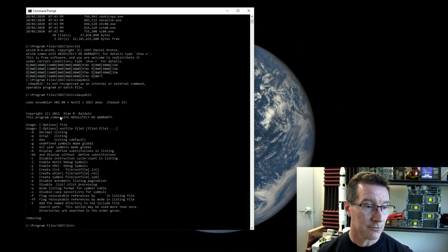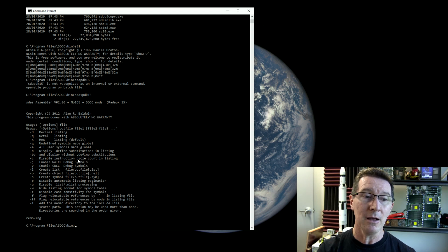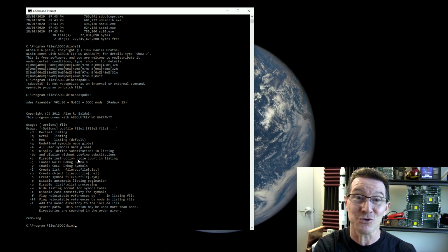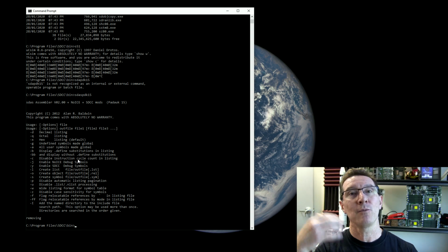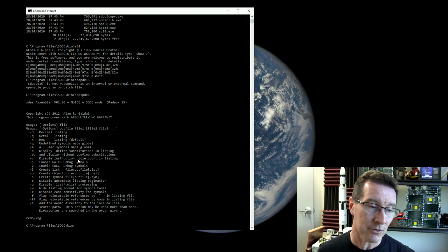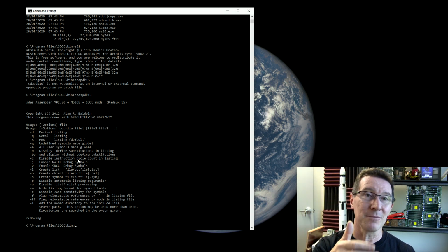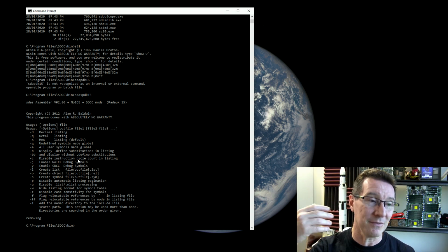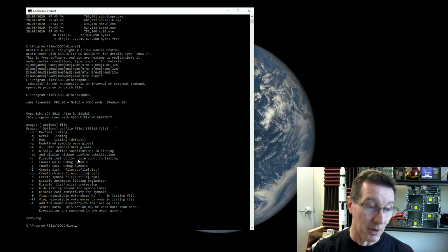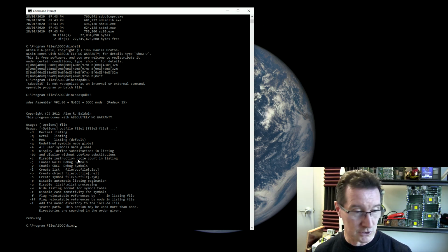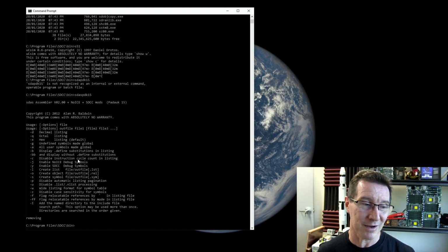That's the assembler written by Alan Baldwin. Good on you, awesome effort. Absolutely no warranty implied. But yeah, this is what the compiler will call. It'll call up this assembler, which does the hardcore work, when we tell it to target the Padauk microcontrollers. The whole idea of the C compiler is that it converts the C into assembly language, and then the assembler compiles it into the binary. So unless you want to write assembler, you wouldn't muck around with this.